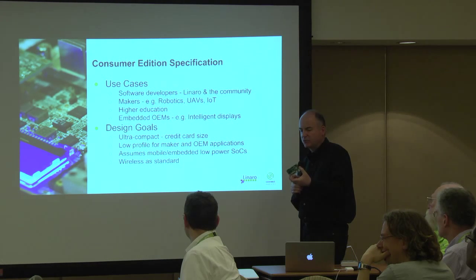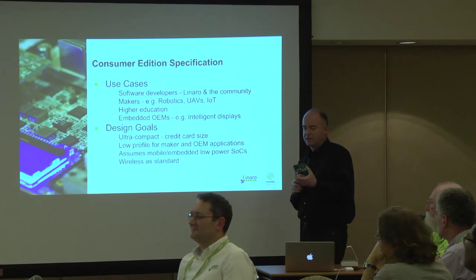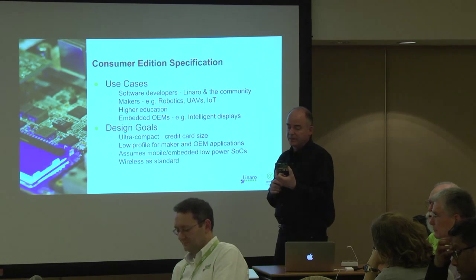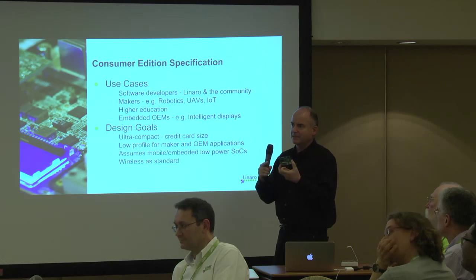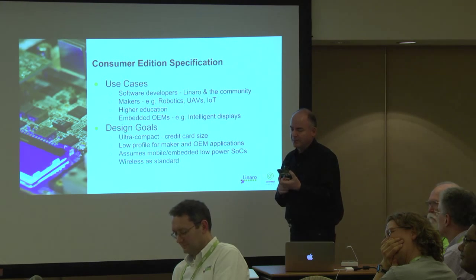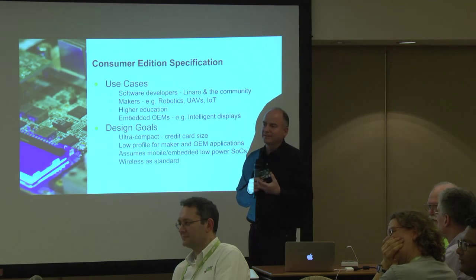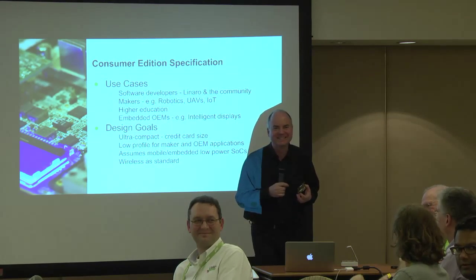This is actually a metric design in terms of its dimensions, and it's dimensioned for M2.5 screw holes. The reason is that when you have a credit card space, the screw holes actually take up a lot of space because you need the spaces around them. So we went with M2.5, which is bigger than M2 and not as big as M3, but it was a compromise. It's fairly obvious, right? Arndt?